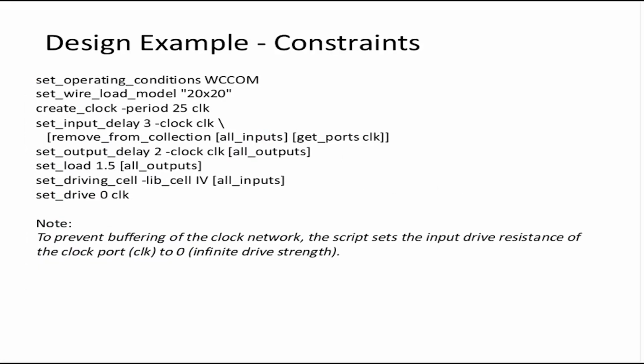So let's look at the script. The first command sets the operating condition, and the second command sets the wire load model. We set the driving cell to be this buffer IV, which is written in the specification. Design Compiler, PrimeTime, all such tools use the Tcl language as their base, so all the commands and expressions here are Tcl expressions.